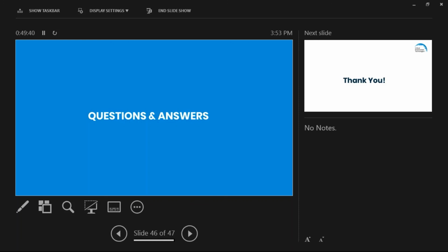No, the actual code, the Canadian code, states that it must have an audible and visual notification appliance, and that's it. An audible and visual notification appliance. That can be as simple as a horn strobe, or as complicated as a remote display with a horn strobe. That's up to the engineer of record or the engineer having jurisdiction, what they want. But the code states simply an audible and visual notification appliance.